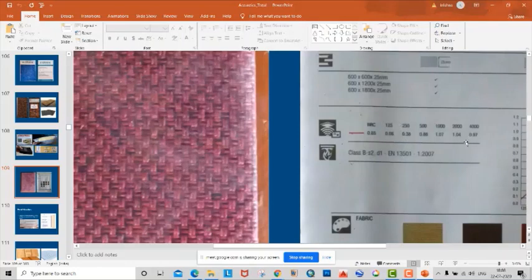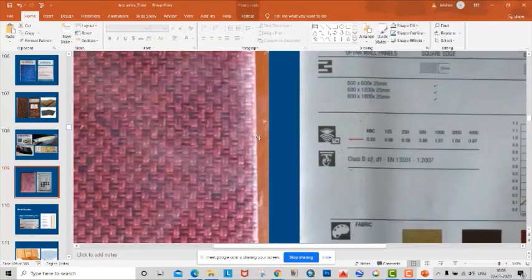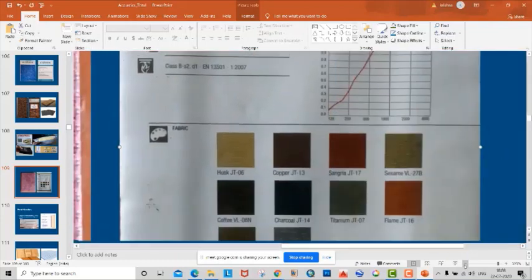But if we see higher frequencies, 1000 Hz, 2000 Hz or 4000 Hz, we have even more than one; the sound absorption coefficient is 1.04 or 0.86. So for higher frequency this is performing very well, but for lower frequency, 125 Hz or 250 Hz, it is not performing very well as a sound absorber, right? So we need to know this kind of detailed description of the material.